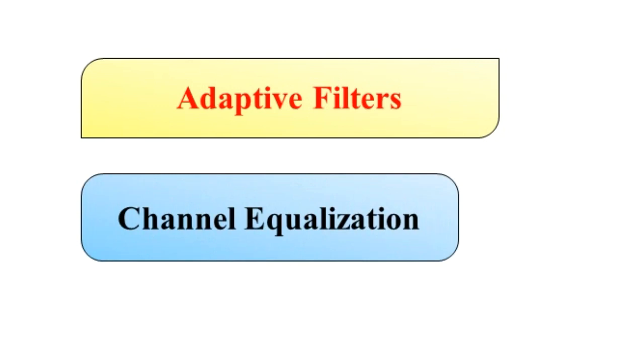After the use of the gradient adaptive lattice filter for efficiency, just now we have addressed the joint process estimator, so that the applicability of the designed adaptive filter will be acceptable to a variety of more applications. Among all these applications, channel equalization is the most important and popular application, where the use of adaptive filters benefits a lot. Therefore, the current topic is titled channel equalization.